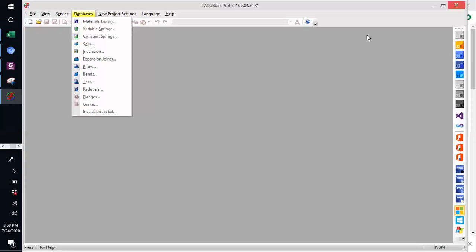You still have some form of little leakage because metal and metal are both rigid. So we now have a material that is more flexible to be in between the two metal to metal contacts, so that no matter the fluid going inside the pipeline, you don't have leakage at the point of intersection of those two metals. So that is what we call a gasket.